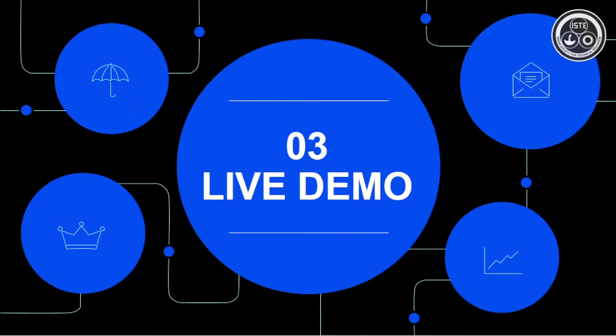Now you can see that's ThingSpeak by official MathWorks. I already installed it. If you have not installed it, you will be using it for the first time, right? So click the install button and install it. This ThingSpeak library is used to initiate the connection from the NodeMCU to the specific channels and API keys. I will be telling what those things are.